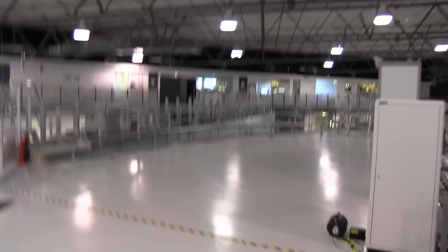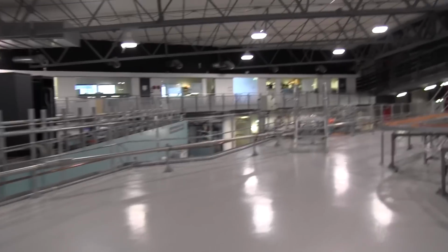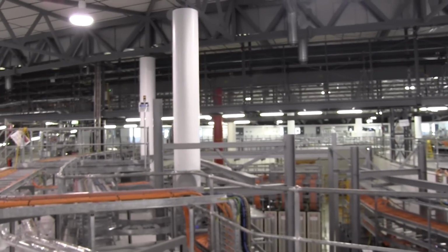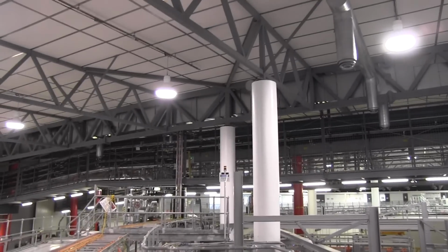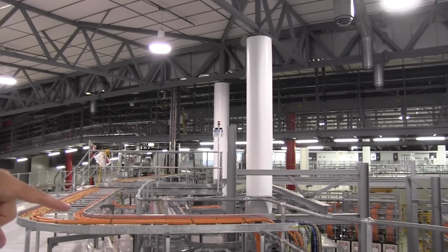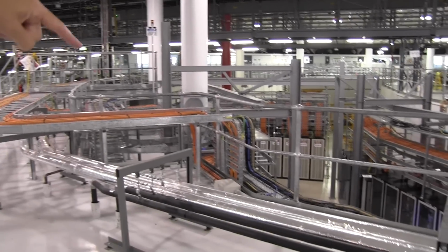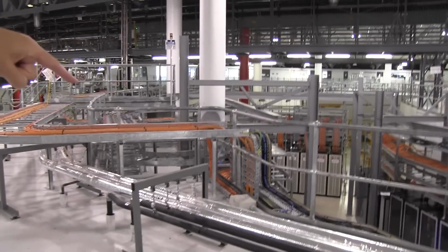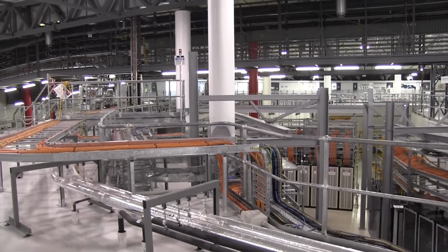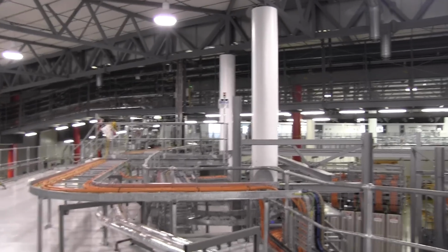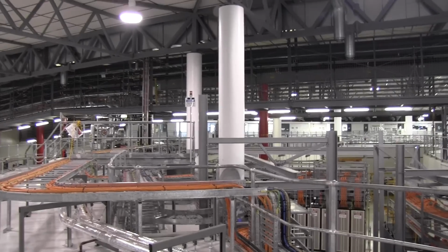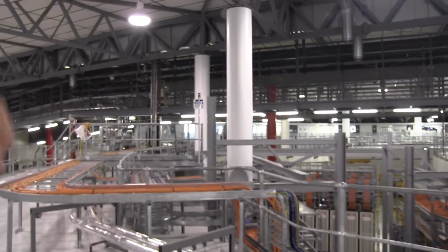And Tom said this whole facility is floating or is damped in some way. So if you look at the pylons here, they are connected deep down into the earth on one end and up into the building on the other end, but they are decoupled from the concrete floor where the accelerator sits. Got it. So if the building vibrates, then that vibration is damped by what is serendipitously a clay soil surface underneath, and that also damps out any road noise.